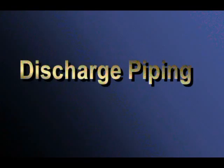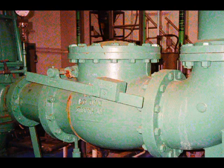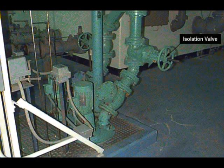There are also some important features and concepts that should be kept in mind with respect to discharge piping. Starting from the pump, there should be a concentric reducer that enlarges the discharge pipe size to at least one size larger than the flange at the pump. The check valve prevents a wastewater flow backwards through the pump. Material moving through the pump in the wrong direction can damage both the pump and the motor. Just past the check valve is an isolation valve, which allows for removal of the pump and maintenance of the check valve. The isolation valve should be downstream of the check valve to allow removal of the pump or the check valve.